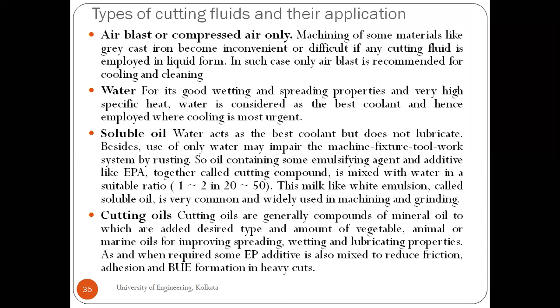The lubricating factor in case of the chip tool contact is not provided by water. So some water soluble oil can be added with water, and that oil acts as a lubricant, and water in it acts as the coolant, as well as the cleaning part is taken care of.